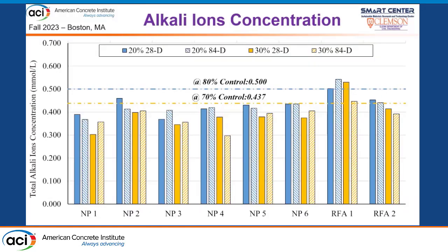And these are the alkali ion concentrations of the pore solution. The alkali ions include potassium and sodium. Here we have two replacement levels, 20 and 30%, shown by the blue and yellow colors respectively. The solid fill and the pattern fill represent 28 days and 84 days respectively.